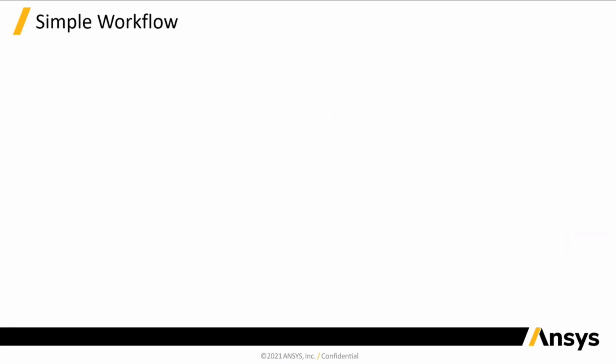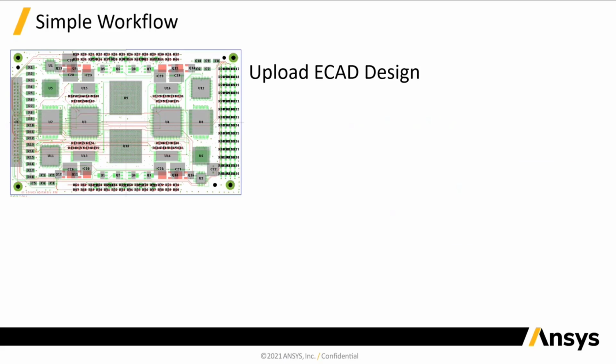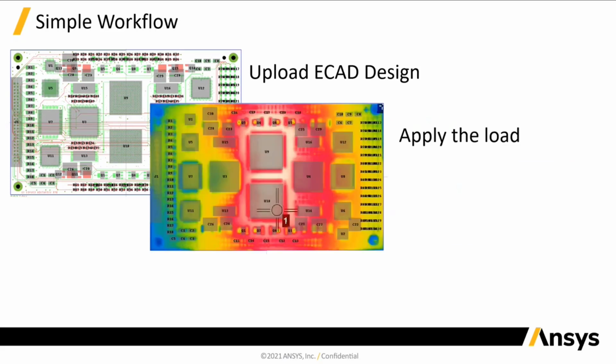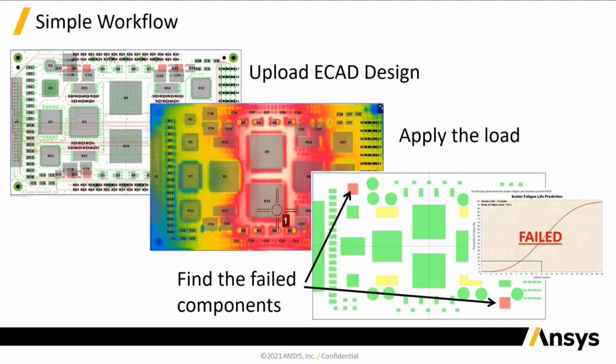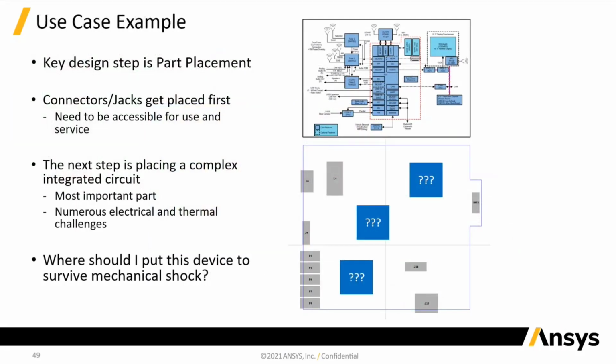So just to summarize, Sherlock is a very simple workflow. You upload your ECAD design and associate all the components with it. You apply your loading to the design, you simulate it, and you find any components that are not meeting your requirement or are very close to failing on your board. And then you can start to mitigate and understand how you would improve that. And this is possibly best shown through a very simple case study.